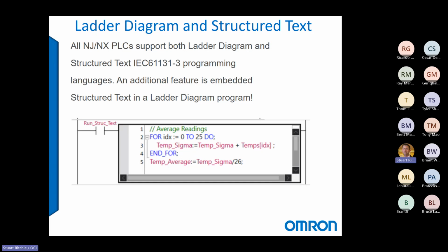One thing we do differently, and it's actually a huge advantage in many cases, is we can have the best of both worlds. I personally prefer ladder, but there's lots of opportunities for structured text to save time. And jumping back and forth between a structured text routine and a ladder routine can be a bit of a pain. So in Sysmac Studio, we can actually embed structured text in our ladder logic, and we can conditionally execute it with ladder logic instructions.